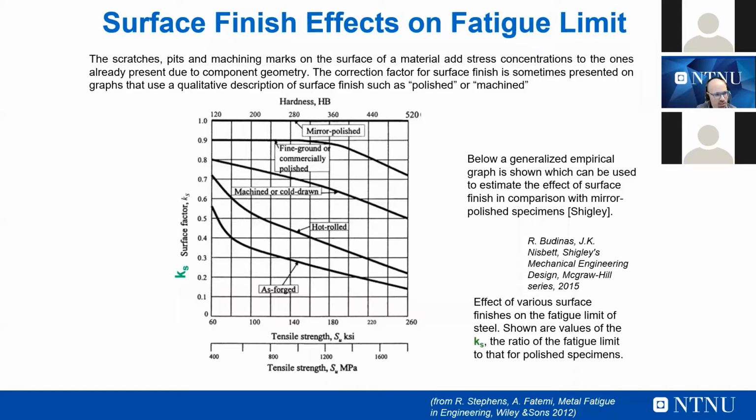So we have to consider this aspect also in the cost for the design, because sometimes we are facing the problem of costs for additive manufacturing, and sometimes it's not a good choice to increase the strength of the material if you are also not treating the surface properly. Sometimes it's better to use a low performant material and treat it with, for example, not a very detailed surface finishing. This reduces the cost and you have the same effect.